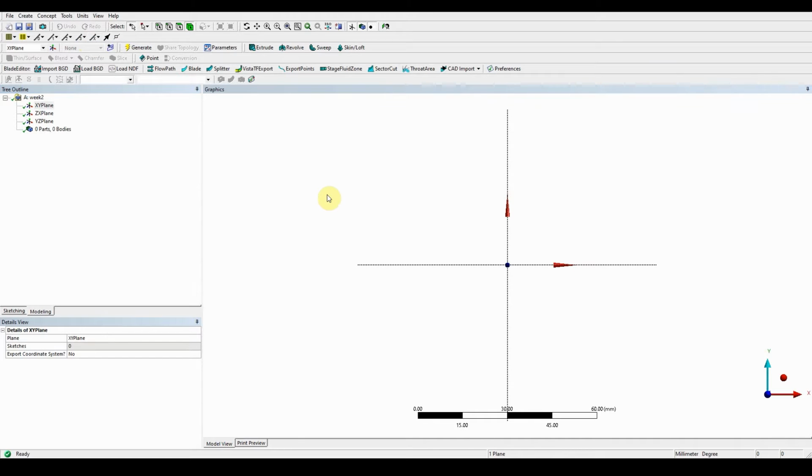Now what we're going to be doing here quickly is just doing a square rectangular box section, and this is going to be our wind tunnel, and in that wind tunnel we're going to be placing a pole, which is then going to be forced with a velocity of 100 meters per second coming on, and the pressure forces on that pole is then going to be transferred as a boundary condition to an FEA analysis, so we can do static structural to look at the deflection. So quickly, 2 ways of doing this.